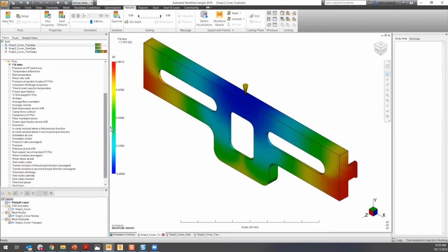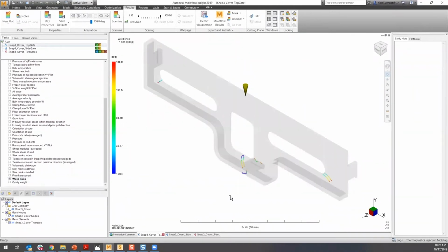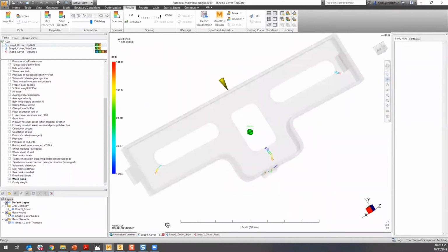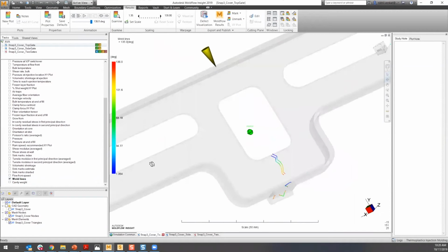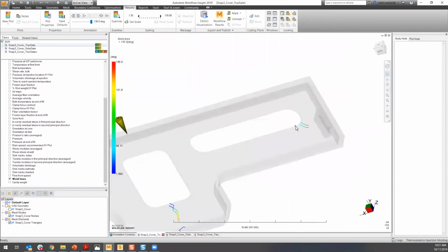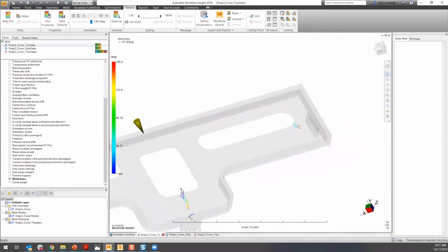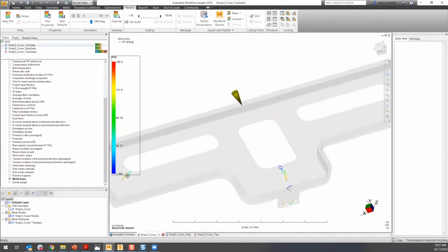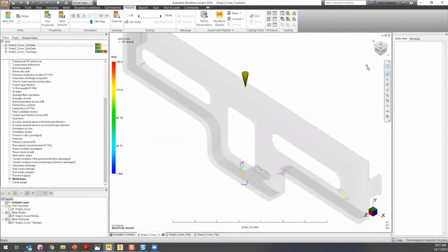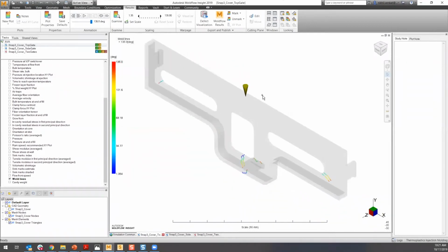Now, some of the other things we can look at, I did mention weld lines. So we need to look at where the weld lines get formed. In this case, the weld lines are the ones that you see over here, the ones that you see in color. It may seem intuitive that these are going to be the weakest areas of the model, especially regions like this. If you've got some experience with FEA, then you'll be able to tell quite intuitively that these regions would be the weakest regions. And this really confirms that suspicion. It confirms that intuition, I suppose.